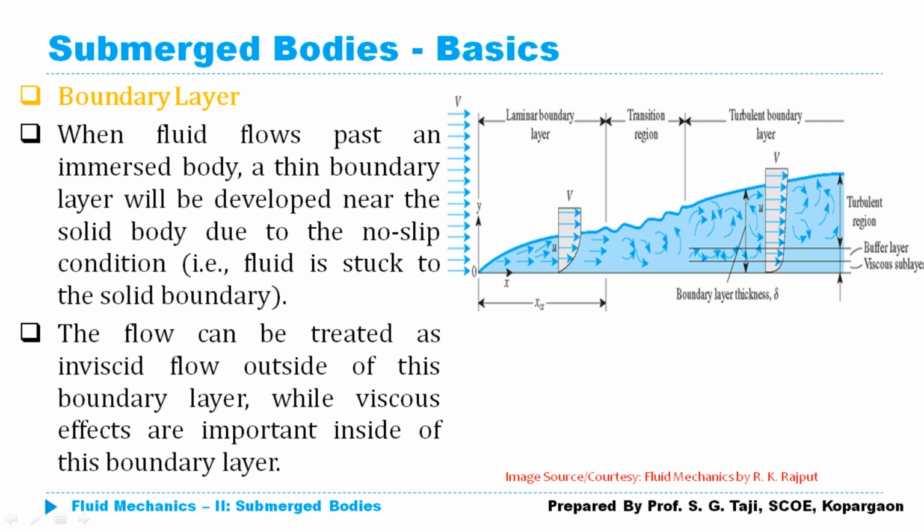So if I am considering a boundary here, and if this boundary is at rest, then whatever liquid comes in contact with this boundary will attain whatever velocity this particular boundary has. So if the velocity of this boundary is 0, the layer exactly near this boundary will attain that same velocity due to the adhesive forces. And when my layer 1 comes in contact with that boundary, it will attain 0 velocity.